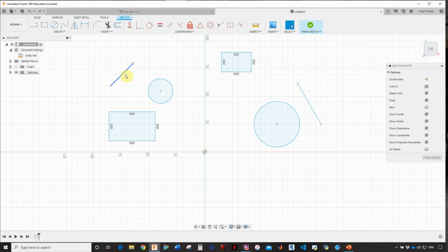Okay, now in this case, a line doesn't really have any depth to it. It doesn't have an area. It's simply a line connecting two points, right? But if I were to create something like this, notice how it's now two lines, but because this corner and this corner are not closed, then this is not a closed area, right? Now, if I get pretty close, but not quite, it's still not a closed area, right? So I still cannot use this to create a solid, okay? So this has to be closed with this other one. Now, there's a couple of ways we can do that.